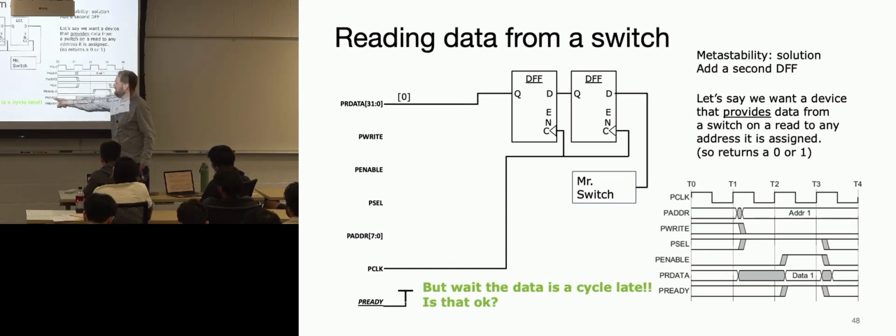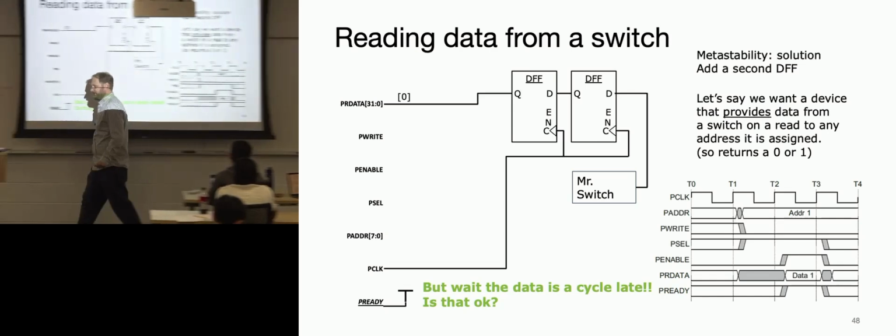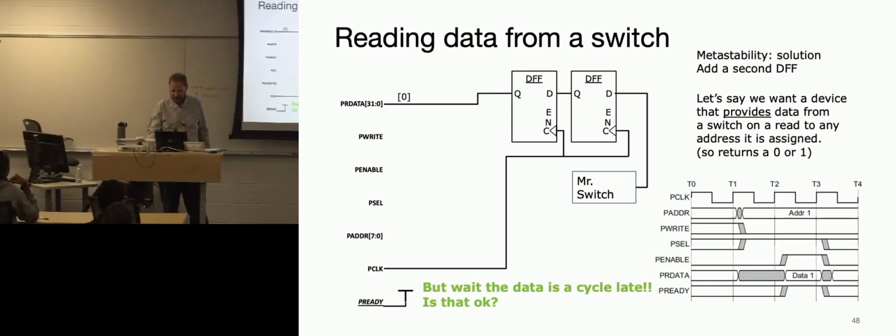Because this is the read data. This is the data coming from the device, and we're just saying that it was unknown or undefined there. It wasn't ready until this. This is what the circuit diagram from the manufacturer is saying. It doesn't matter what the data was, it could have been anything. It's undefined until P-ready goes high. And the only reason P-ready goes high is when all these other signals go. Then it has the opportunity to go high, and that is when the data is valid. It could be ready for a long time beforehand.